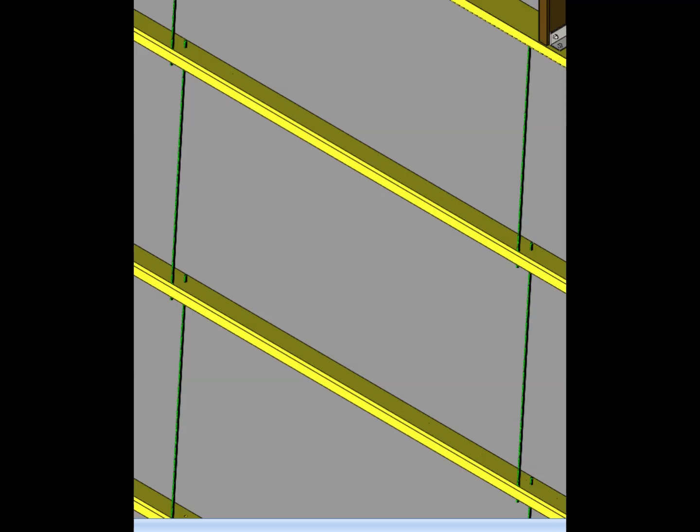Here, instead of looking at the complete building or the complete side wall elevation, we are zooming into the actual 3D structural members so that the arrangement can be understood clearly. In this close view, the yellow horizontal members are the side wall framing members, while the green vertical members running between them represent the sag rods shown in this model.